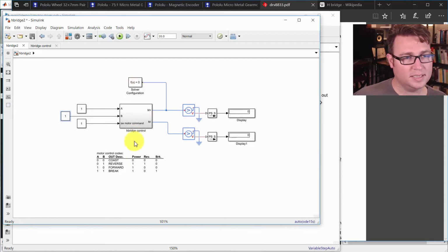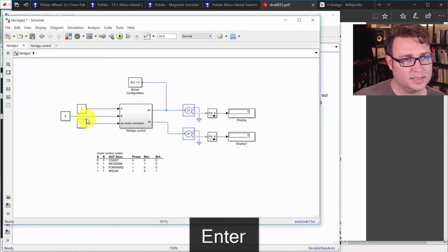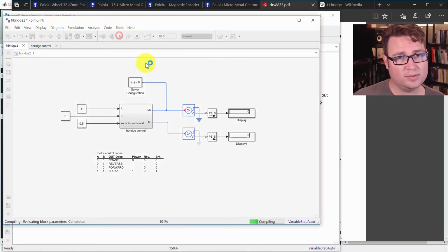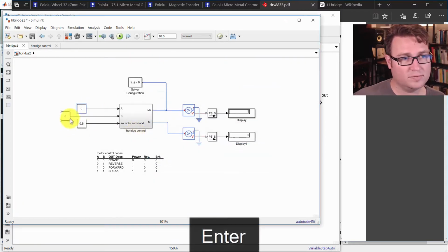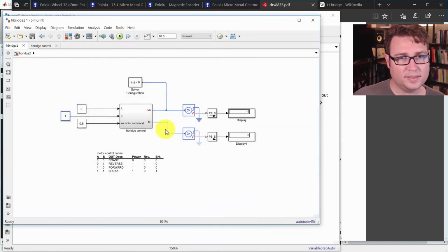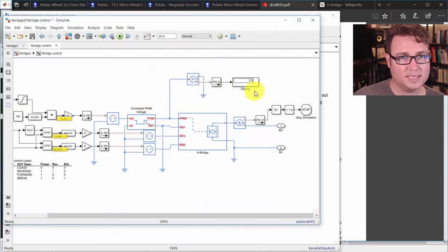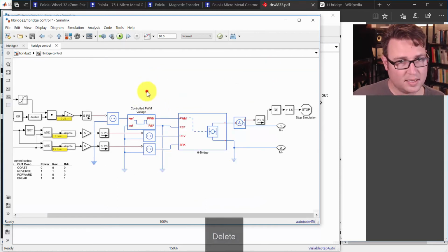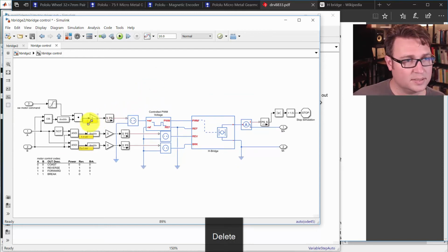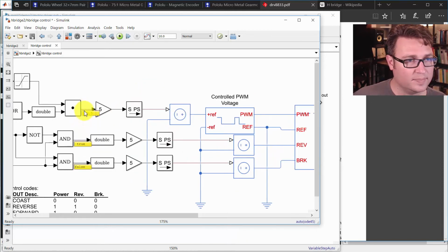which it does. Okay, now one more thing I want to try before we leave is half. So this is half power. Output at 100% is 6 volts, so we should get an output of 3, which we do. And if we go back to reverse, all right, 3. Okay, and I'm going to take this guy out. I was troubleshooting that. Good. Everything else is good.